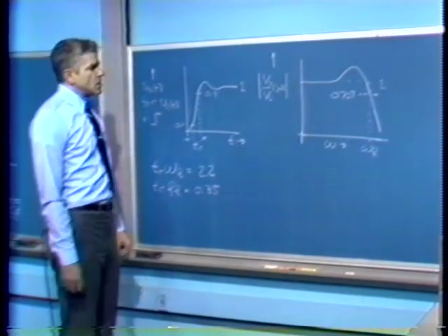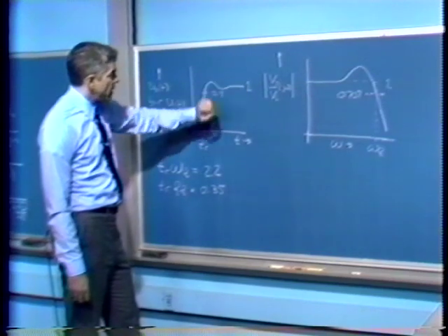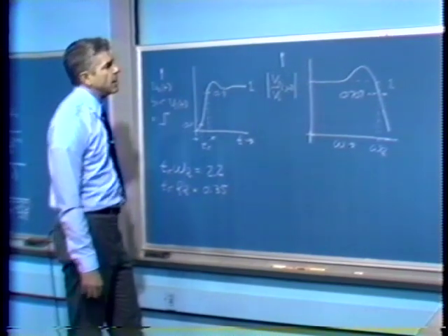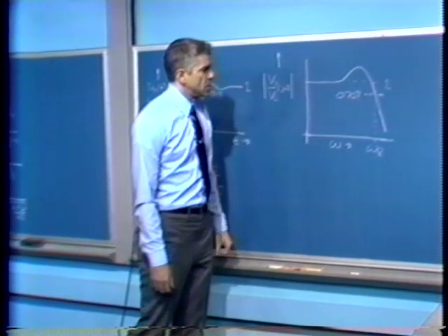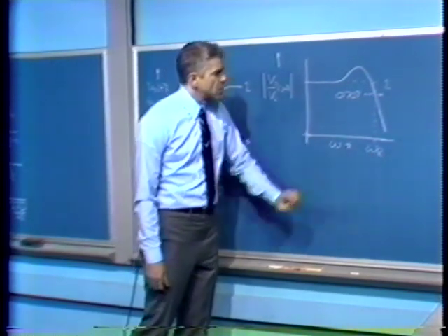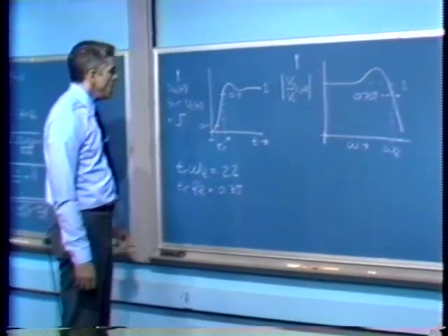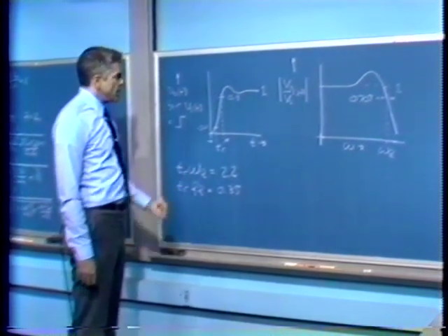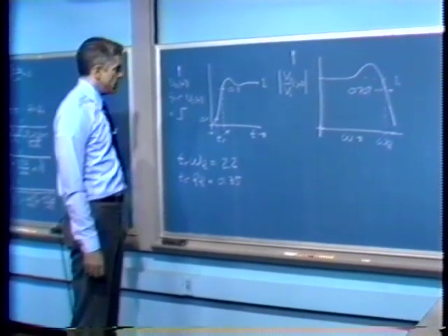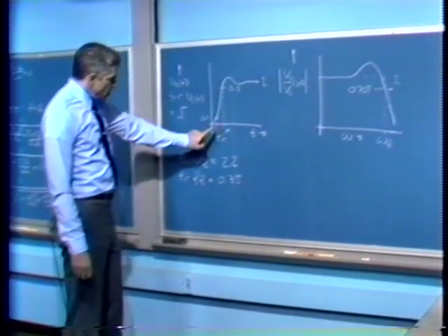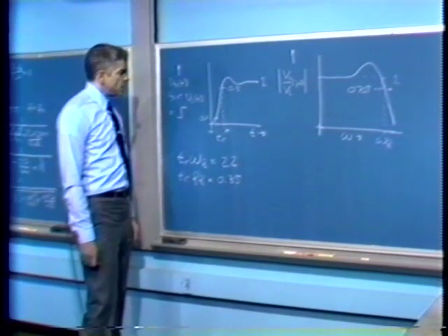There's some sort of correspondence between the time that it takes for a step to reach final value or some fraction of final value in contrast to the frequency response of a system. Again, a wider frequency response implies a faster time response. And in particular, that relationship is such a good one that I think it's worth emphasizing even beyond the material in the book. One of the things that's very easy to measure, as I indicated before, is the step response.